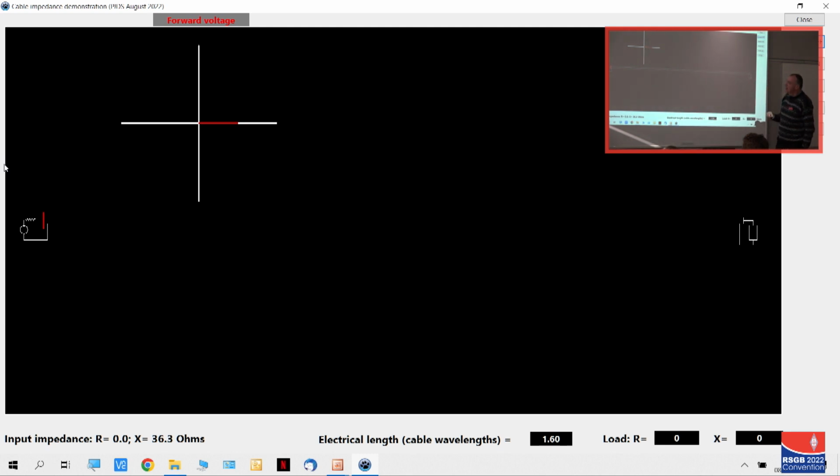Now, what happens when you turn on your transmitter? It launches a wave at 10 megahertz or whatever frequency you're using. It launches a wave which travels along the feeder to the other end. And that wave, if you think about it, when it's all up and running, the voltage here is going to lag behind the voltage here, because what's here left some time earlier than this point.